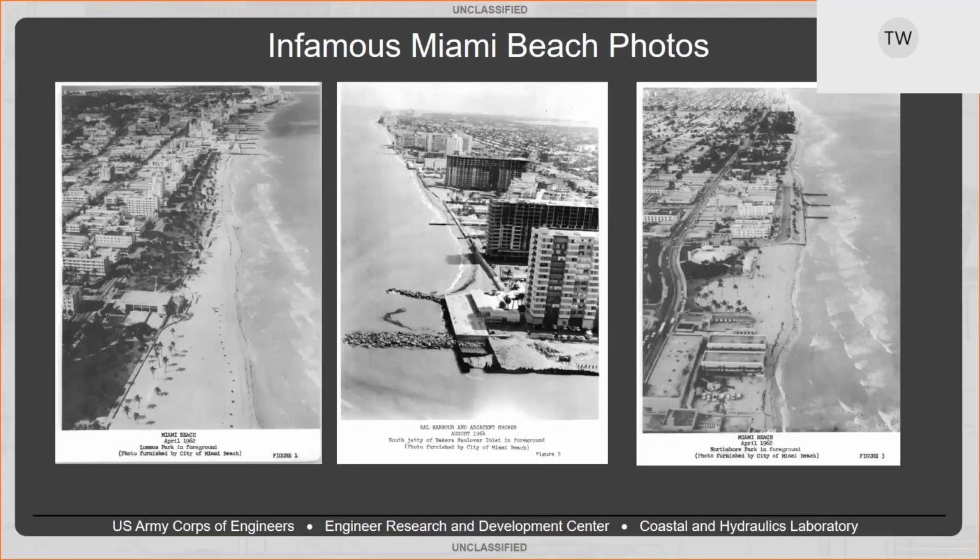But that other system that we're pursuing in the swash zone, the sand shifter, we're proceeding with because the same people that built and designed the Nerang bypassing plant also patented this sand shifter technology, where it bores, and you saw that crater that it made, but the Bedload Collector just sits there and the sand drops in by gravity as opposed to the fluidizing system going down into it.